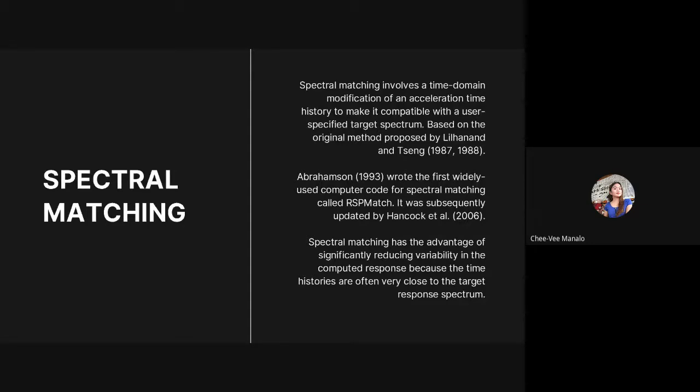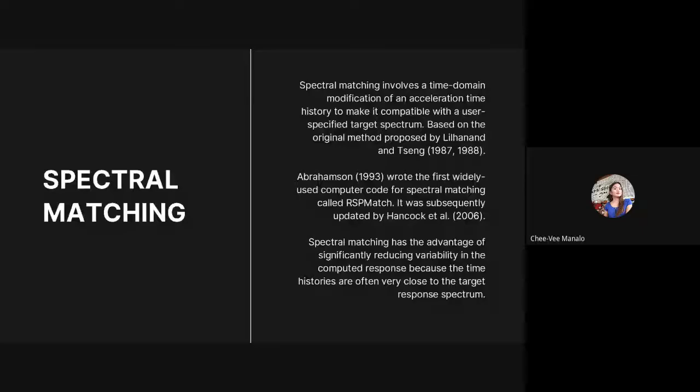When we say spectrum, it is the curve that shows amplitude and phase as a function of frequency or period, or how much of each type of shaking there is from an earthquake. We will see a sample of a spectrum in the next slide.